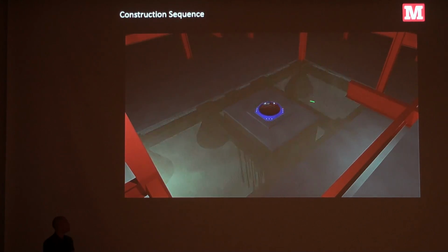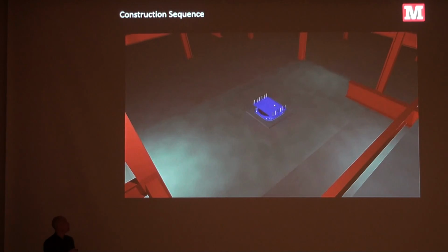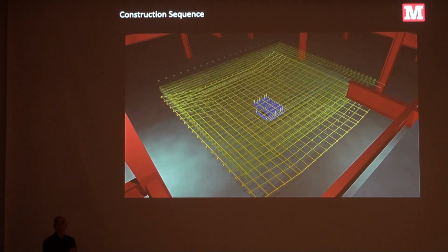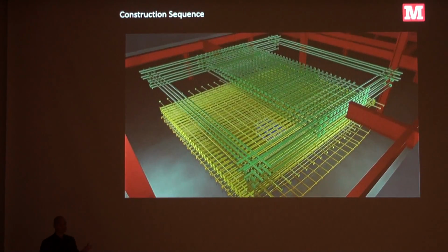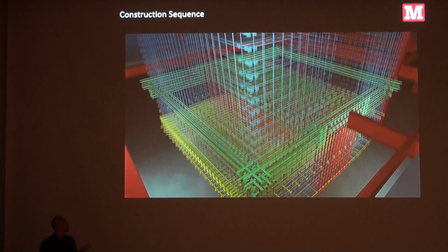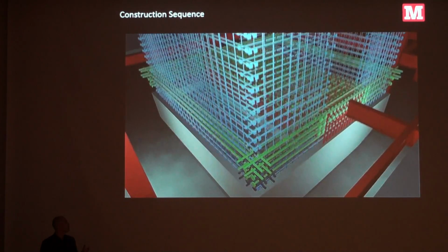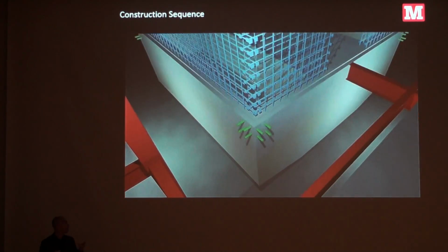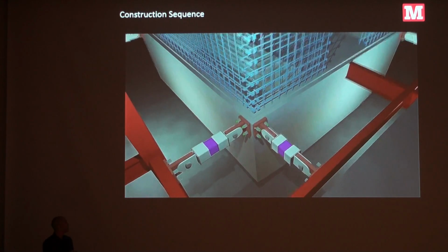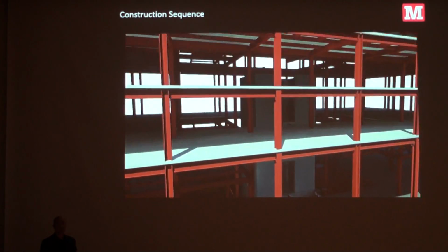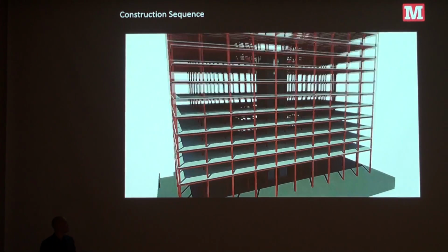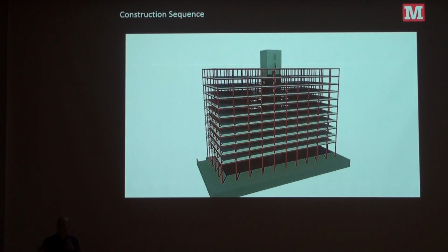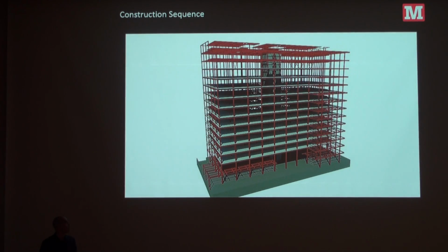This is a base isolated pin. This is what this element sits on. Think of it as a pivot point. That is the foundation that sits on that pin. And then here you see the spine connected to the floor with steel dampers called buckling restraint braces. They accommodate the deflection compatibility and bring the flow of forces in and out.